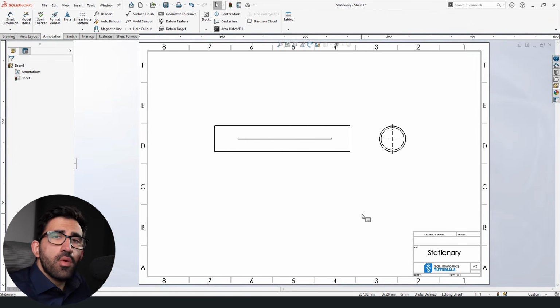Okay, the last tip I want to include in this video is auto dimensioning, and it works only if you have already assigned actual dimensions to your model when you model the 3D part. You cannot just not do anything when you're modeling in 3D and then come back in drawing expecting SolidWorks to add the dimensions that you want automatically. It doesn't work like that.